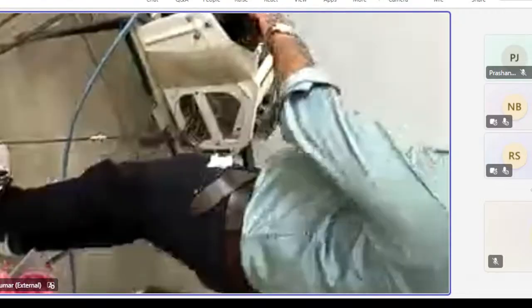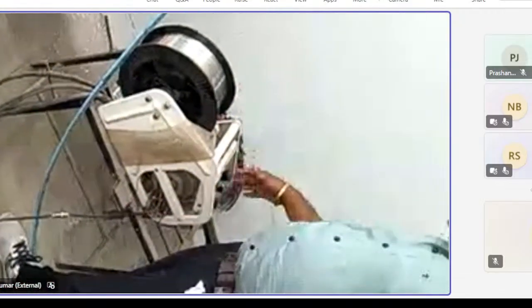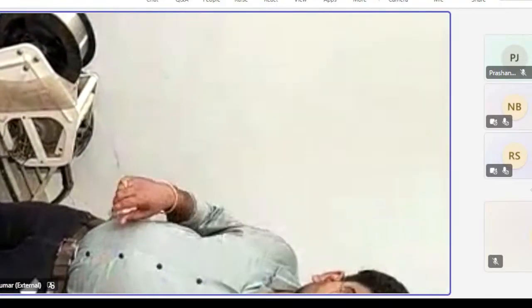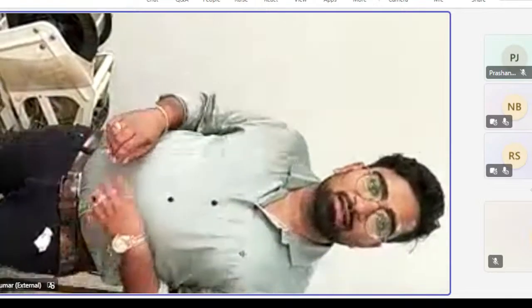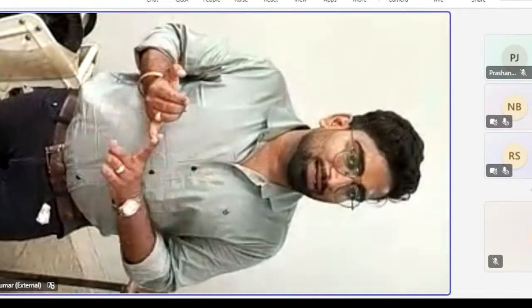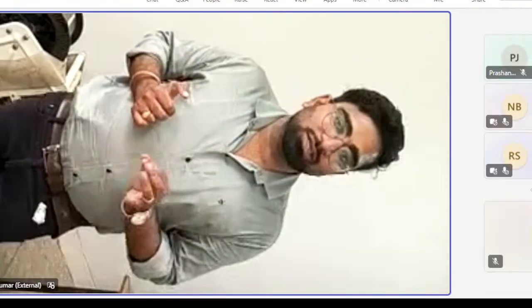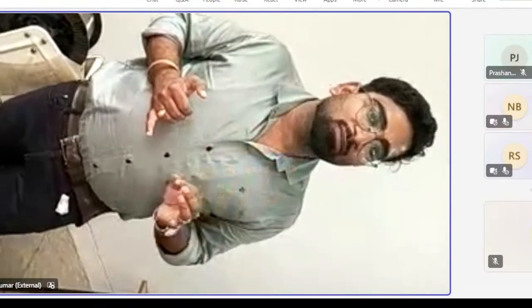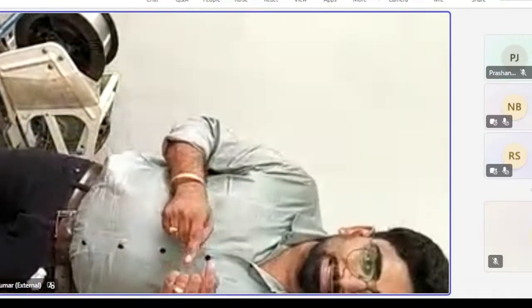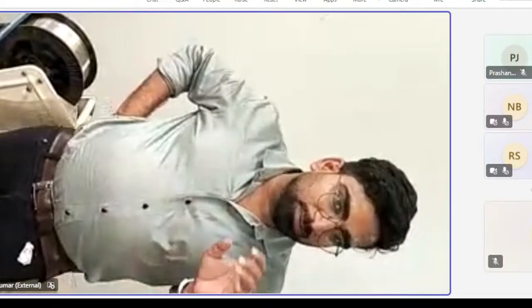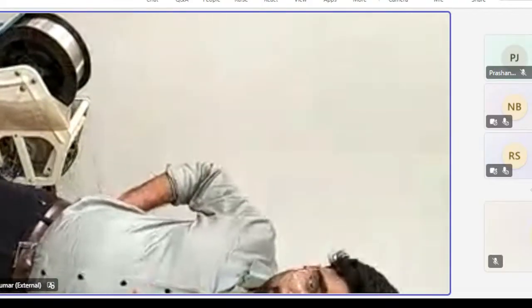Another part is the wire feeder that we talk about. Along with that, the wire comes through the rollers into the torch, and the roller should be as per the wire dimension. Keep in mind what I have said, that the roller diameter should be as per the wire dimension. Otherwise, the wire will slip, it will bunch up over there, and your experiment will fail.